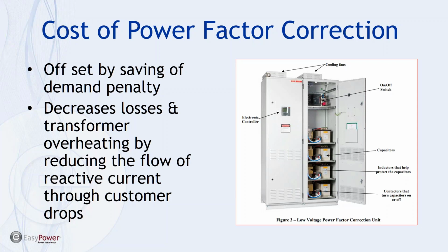So over the last 20 years, power factor correction was promoted, in fact, as the green solution with the shortest payback over anything else. What it amounted to is that inside of my plant, downstream of my point of connection with the utility, I would install power factor correction capacitors, which allowed the reactive power, once my capacitors were charged, to recycle inside the plant, thereby eliminating the need for that reactive power to flow in and out of the utility connection.